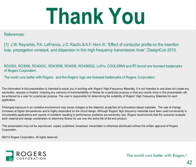Okay. As the circuits age, does their thermal conductivity change? If so, by how much? Yeah, it does, actually. There's a lot of properties that change as the laminate changes, and what's kind of ironic is as the laminate ages, generally the thermal conductivity actually increases a little bit. And it could be because the cross-linking of the thermoset is becoming more tightly cross-linked. It's not a significant difference, but there is a little difference. But as strange as it may be, it's actually a little bit of an improvement.